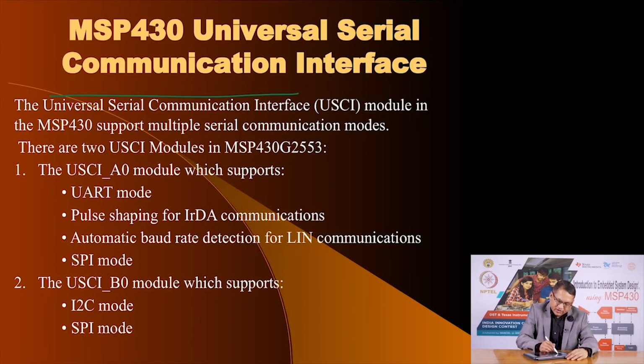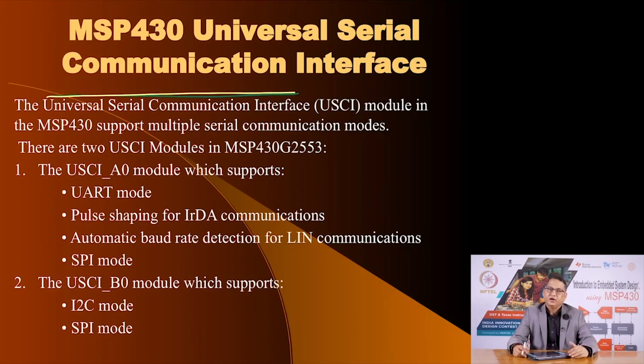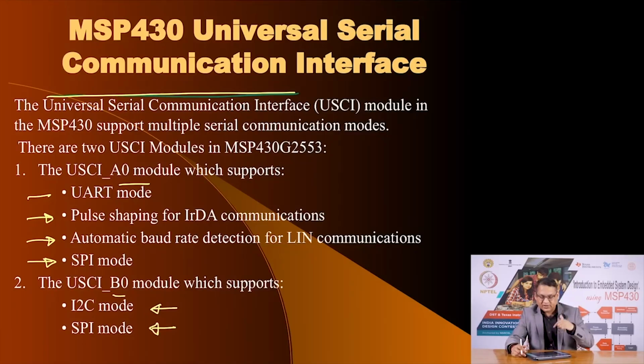The reason why they are called universal is that each of these modules offers support for multiple protocols. The A0 module offers UART, infrared data communication, a LIN protocol and the SPI mode, whereas the B0 module offers only the I2C and SPI mode. So, if you want to have one UART and one I2C, it is possible.